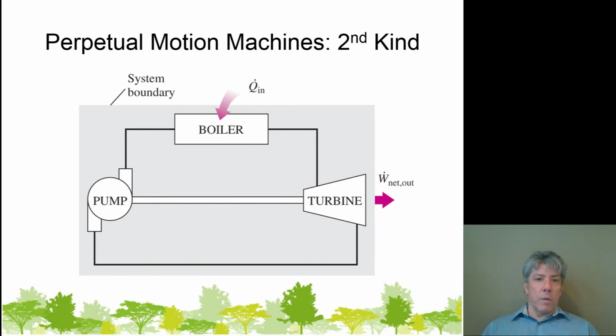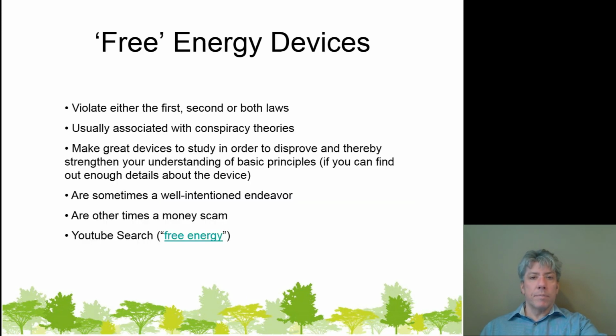Well, this won't work. You won't have a machine for very long, and of course you can't just convert all the heat that comes in into work, mainly because heat doesn't flow from cold to hot on its own or with any machine to help it along. So this is a perpetual motion machine of the second kind because it breaks the Kelvin-Planck statement of the second law. If it broke the Clausius statement, then it would also still be. Of course, it is because they are equivalent statements. They aren't the same statement, but they are equivalent to one another.